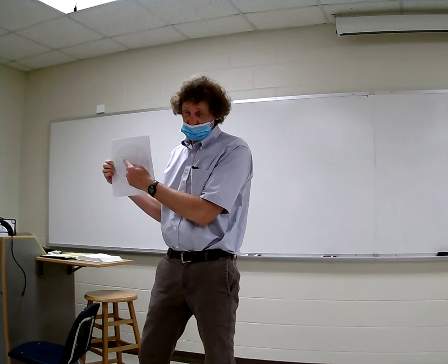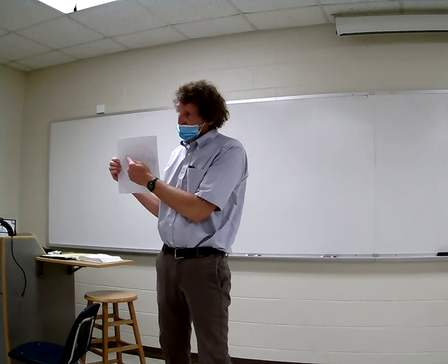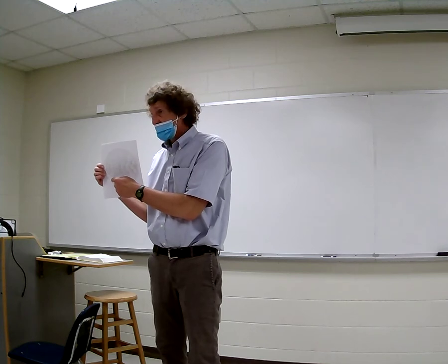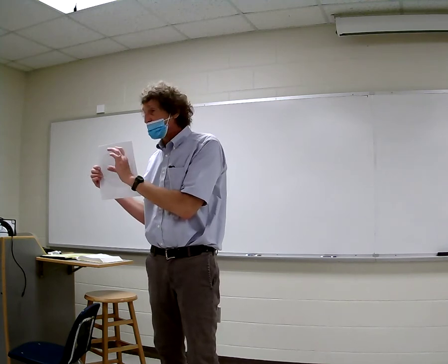Now, because we're in the admittance domain, it's normalized. If it's a positive J being added, it would be a capacitor. If it was minus J, it'd be an inductor. Do you all follow me on this? And that is what is in parallel, correct? Right, that would be in parallel.